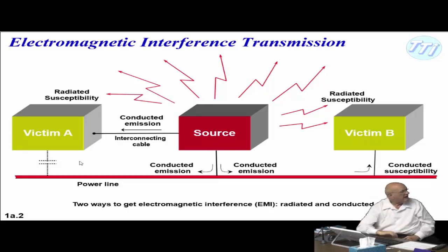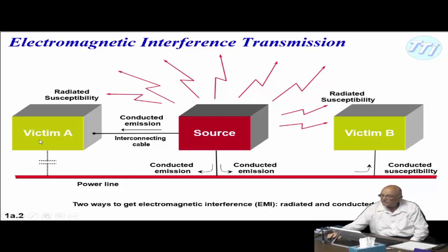So you can actually get coupling from your power line, as you can see here, directly to some other victim or device through the capacitive coupling. Now, this means that you could, in fact, couple through a battery-powered device, couldn't you? You're standing there making a measurement specifically. Energy can couple through your capacitance directly into that unit. And that happens quite a bit specifically.